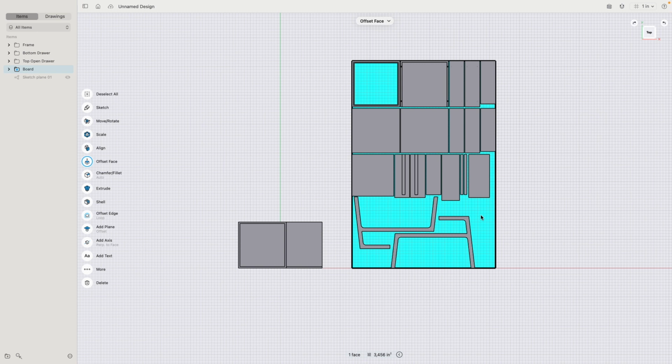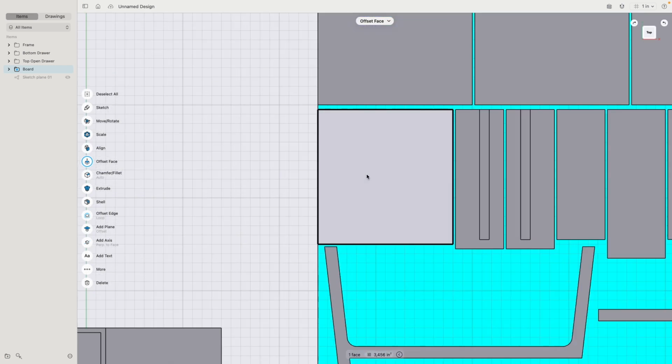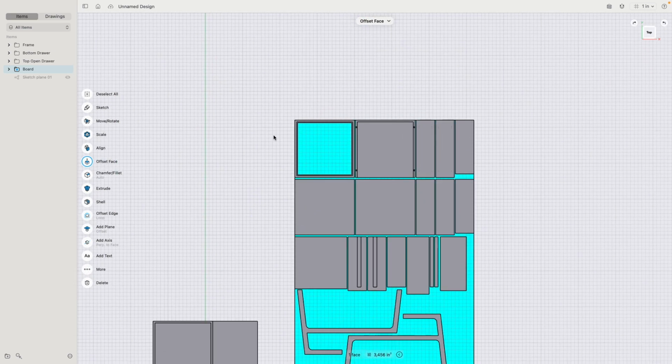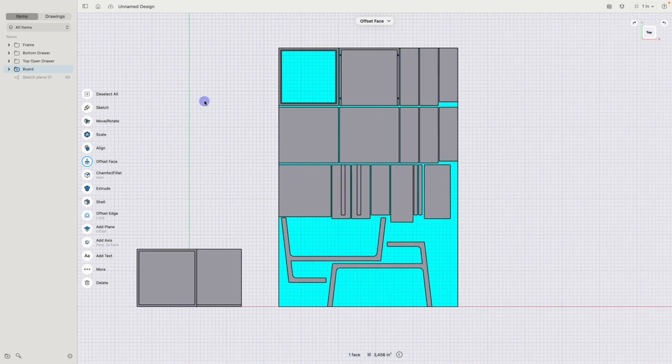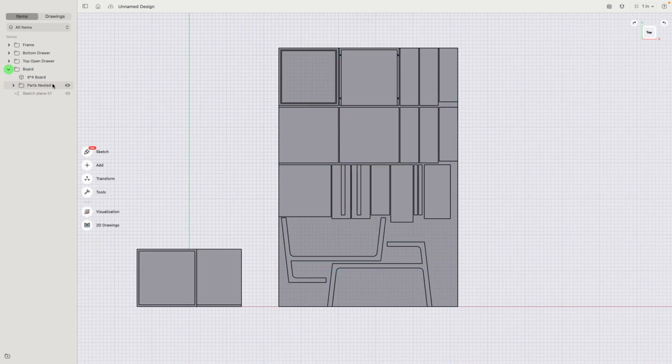The idea here is to position everything so we make most use of our wooden board and try to minimize waste production. Obviously, this opening in between here, the frame, there we have open spaces. There's unfortunately nothing we can do about. But you can see here between the individual horizontal groups, I have 1/2 inch, and then between the parts, I have a 1/4 inch distance. The distance is simply set also to be illustrative. You need to specify this based on your own cutting bits. And I make use of the edges of the wooden board, so I can save even cutting time, because also time is money. This whole process of nesting is also very easy.